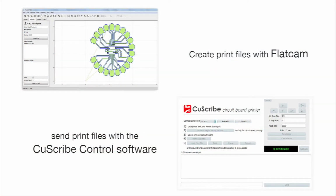We will be using the Flatcam open source software to create print files for the bottom traces, top traces, through holes, and the cutout of our custom circuit board. We will then use CuScribe's control panel software to set up our machine and start printing our board. Software installation instructions are available in the Getting Started section of our website.